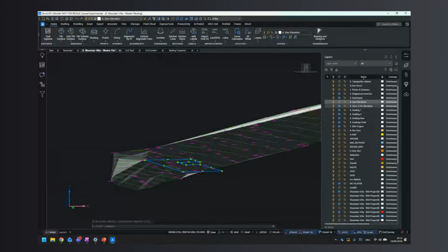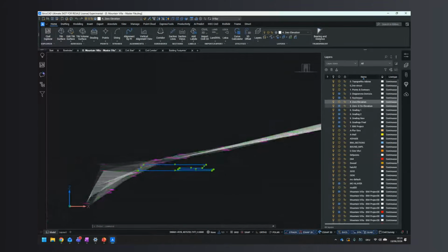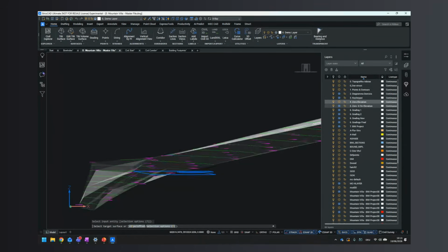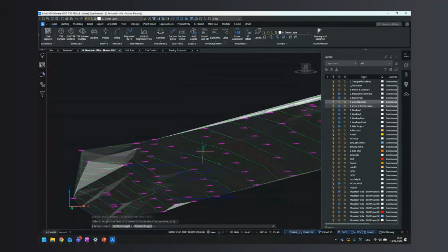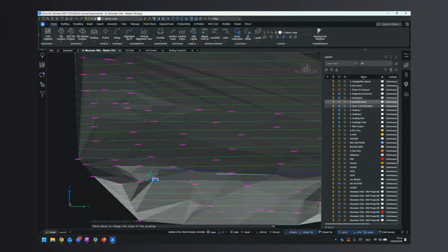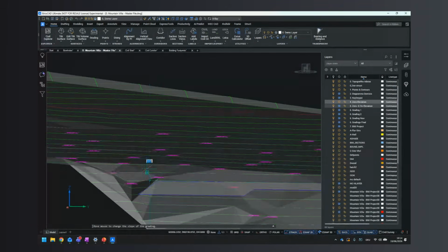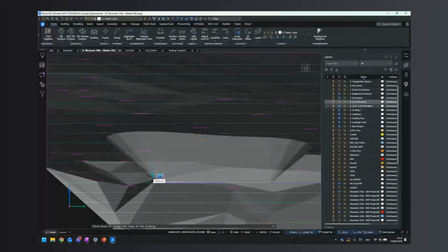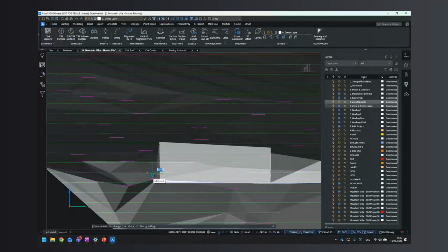So what we need to do is create a grading to calculate the cubic meters of the soil. So again, a couple of clicks will do the trick. Grading, what do we want? An input entity. The target surface is going to be this one, and I'm going to use the entire length of this polyline, spacebar once again. And now I need to move my mouse just to define the angle of attack. Oh, I'm not hitting it correctly. There you go. So 39, no, I need to do 89.